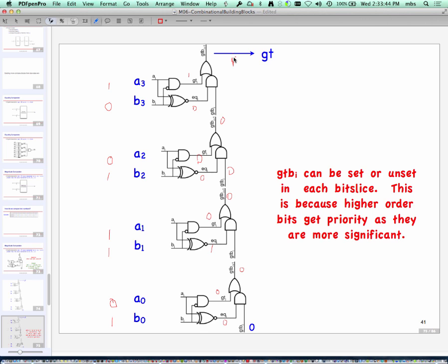And there are both camps. If you read the Wikipedia article that describes this issue, IEEE, which is the electronics organization, I guess they set some standard, which basically picked one definition, which I believe is the one which says an odd number of 1s. But it's ambiguous for more than 2 inputs. For the 2 input case, one way of saying it is checking for lack of equality. Another way is checking that only one input is 1. A third way is checking that an odd number of inputs are 1. That's all the same.